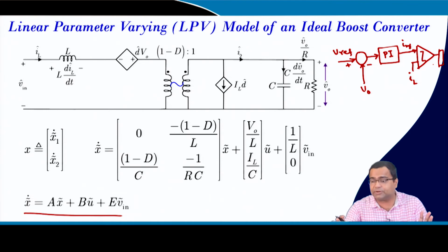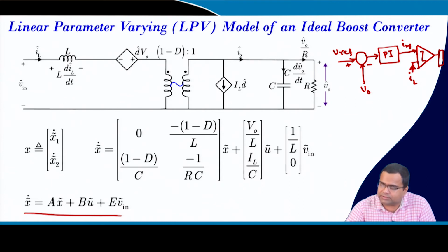I am not going to discuss because this we have discussed multiple times. So, in traditional output feedback current mode control, this is the way. But in case of state feedback control, we can also add one gain block here. That means, after this IREF is coming in, which is compared with our inductor current. Now we have a current loop gain IL, and that is compared.